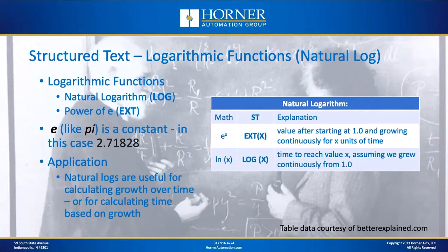So again, when you're talking about growth over time, whether you're trying to calculate the growth value or the time value, that's where natural logs can be useful. And yes, you can use these functions in PLCs, including the Horner OCS, and you can use them in structured text. They're also available in the other languages as well.